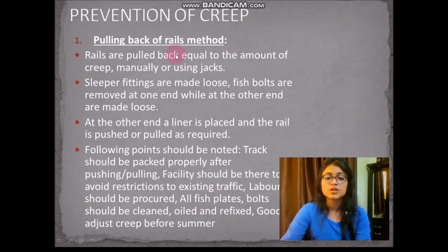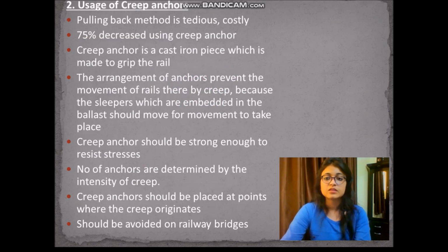You should know that the first method of prevention of creep is that we can pull them or push them according to the creep, either manually or by using jacks. So this was the first method. Second, usage of creep anchors. Creep anchors are another tool which we can use to remove creep. We can prevent creep by using creep anchors.